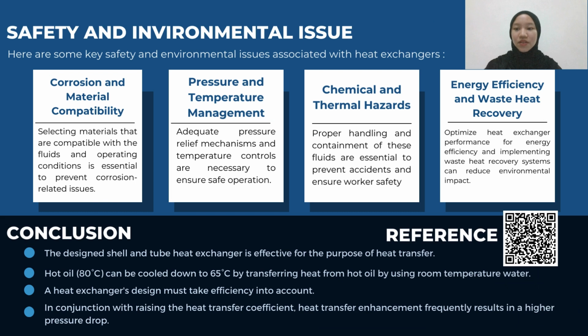Here are some key safety and environmental issues associated with heat exchangers. The first one is corrosion and material compatibility. Heat exchangers are often exposed to corrosive environments due to the nature of the fluid they handle. Corrosion can compromise the integrity of the heat exchanger, leading to leaks and potential safety hazards. Selecting materials that are compatible with the fluids and operating conditions is essential to prevent corrosion-related issues.